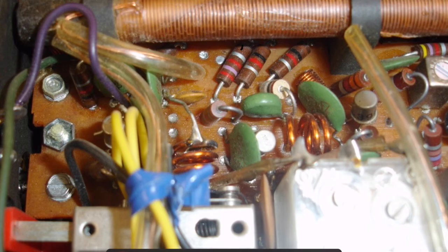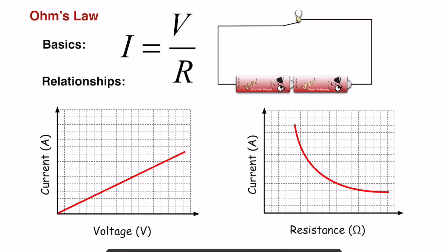So if we see, for instance, a silver band, we know this is band 1, 2, and 3. If the silver's on this side, then we start with this brown one as 1 and 2 and 3. So not only does it tell us the possible percent error, but it also helps us figure out which end of the resistor to start reading from.